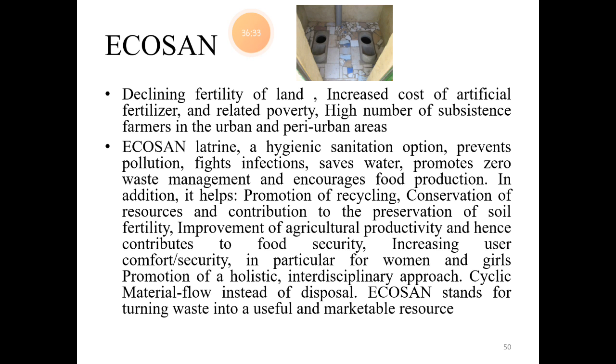Likewise, alternative chambers should be used. During this gap period, the waste gets decomposed into humus by the soil microbes. Until the waste gets converted into mineralized humus, the chamber is incubated. I mean to say, it is just kept aside without usage.